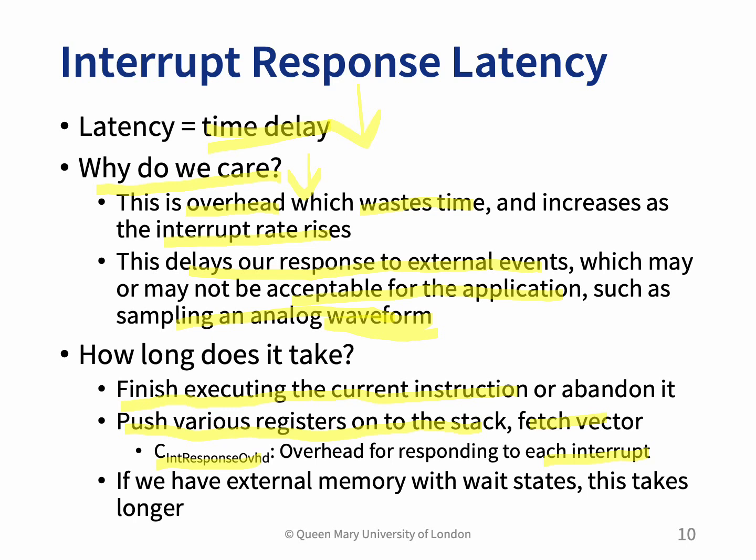The final one, if we have external memory with wait states, of course, this will take longer. If you have lots of interrupts with low priority, and then you have lots of interrupts with high priority, those low priority ones will be in the wait state, or we can say pending state, right? So we don't want that. In other words, as I mentioned in the live lecture, the ISR code should be kept as short as possible to avoid any unnecessary latency.